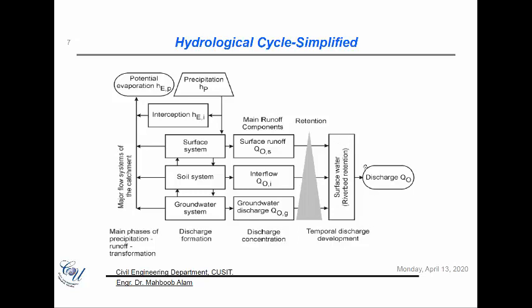And all of them, when combined, are called discharge. Ultimately, whenever we are measuring the discharge at a certain point, at a certain location, that discharge contains the parts from surface runoff, from the interflow, and groundwater discharge. So this thing should be understood.